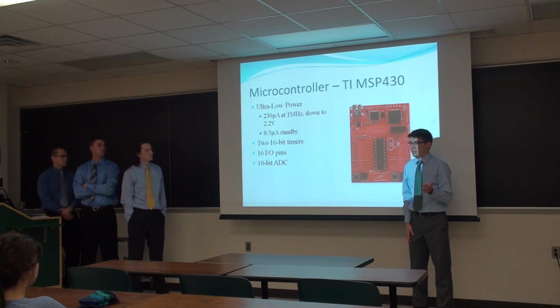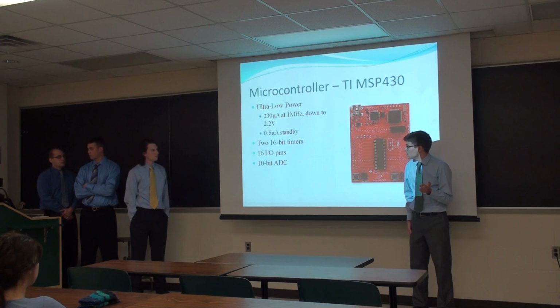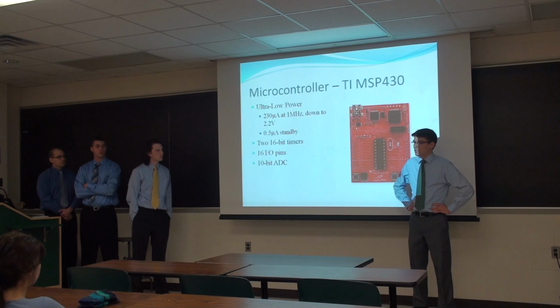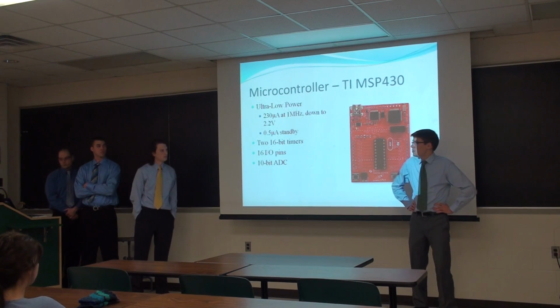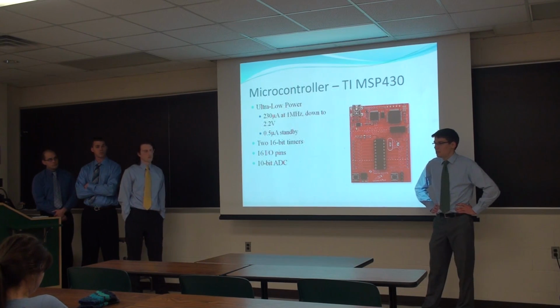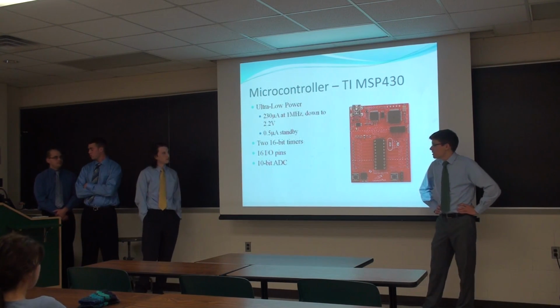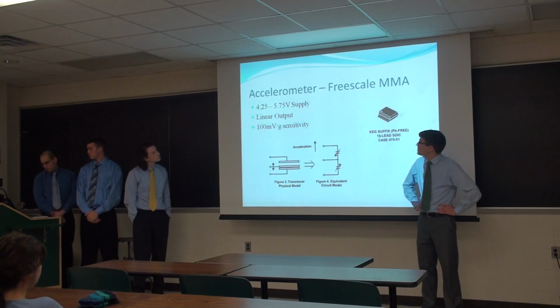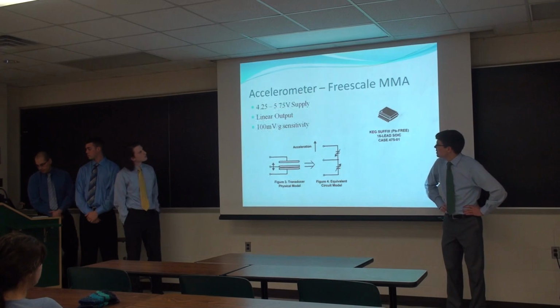We also like that it has 16 I/O pins. There's analog and digital. We're using the digital to drive our LCD, our LEDs, and to take inputs from our buttons, and then we're using our analog pins in conjunction with a 10-bit onboard analog to digital converter to take input from our analog accelerometer, which we're getting from Freescale.